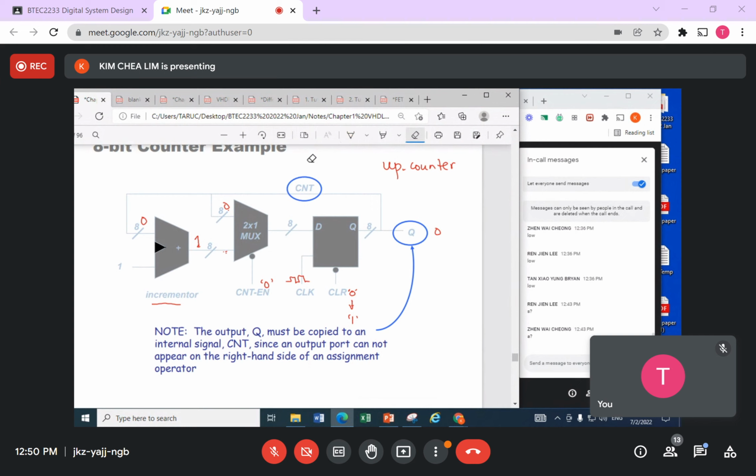Inside here, this 0, with this 0 here will cause this one to become a 1. This is a 0. So if this is a 0 going in, they will choose this one as the output. So when it comes to here, clock comes. 1 will be appearing here. And with this one, back to here. So you find that this one here now changes to 1. I put at the bottom, here changes to 1. First clock pulse successfully increased my counter from 0 to 1.